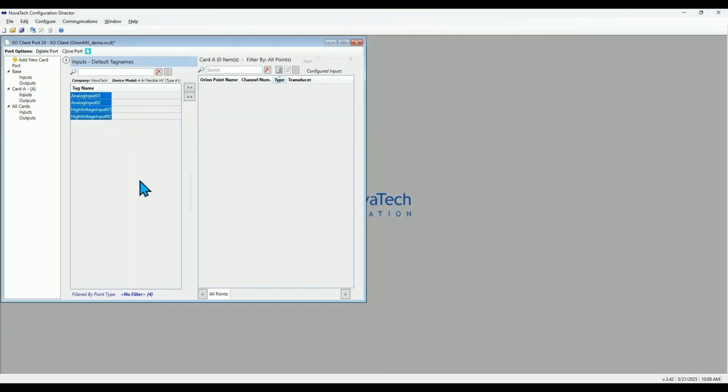And you'll see these are the 4 slots for it, and I'll just go ahead and add them all. And you'll see they display the channel number here. Of course, they're all analog. When it comes to the transducer, there are selectable values here. As Ryan had said, and as he showed on the slide, the inputs 1 and 2 are lower voltage. They are the range of minus 10 to 10 volts. So of course you can select those for inputs 1 and 2.